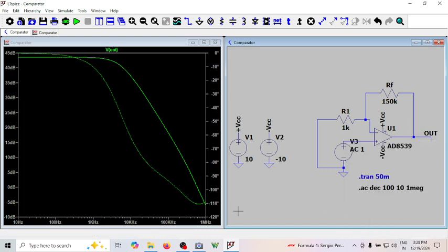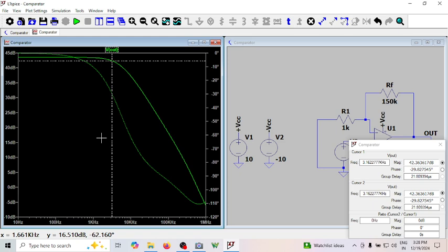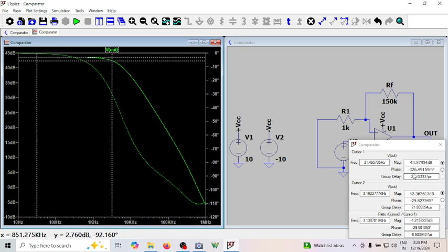More interestingly, just see the phase of this. In the previous cases also we didn't measure the phase. You can see here the phase is almost 0 degree, minus 326 milli degrees. Don't simply go by that minus 326. It's actually milli. Milli means 0 degree, meaning there is no phase shift.